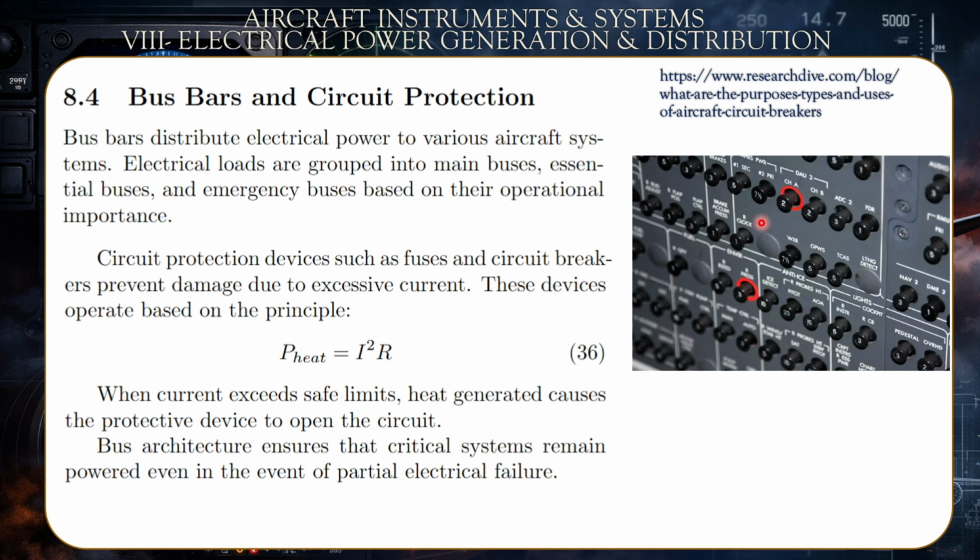In fact, to be more accurate, when we talk about the circuit breaker that is used in residential applications, it flicks rather than pops. This one pops to the outside when the circuit breaker is activated, and it opens up the circuit to prevent overheating of the cable or a potential fire. Meanwhile, the one at your house doesn't pop; instead it flicks downward when the acceptable current is exceeded.